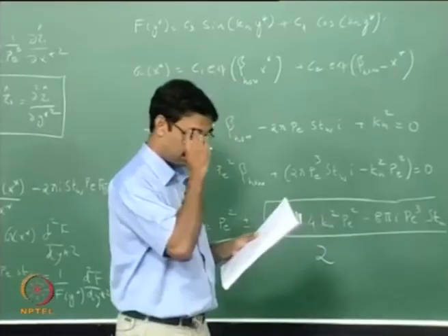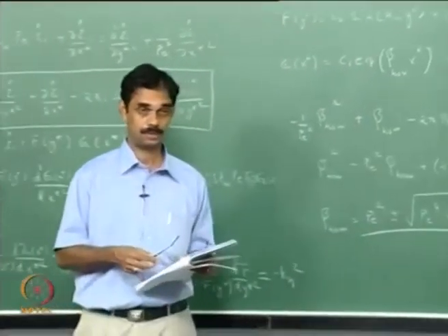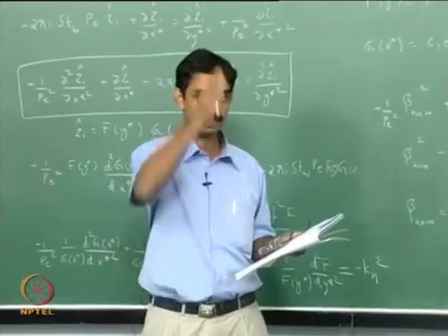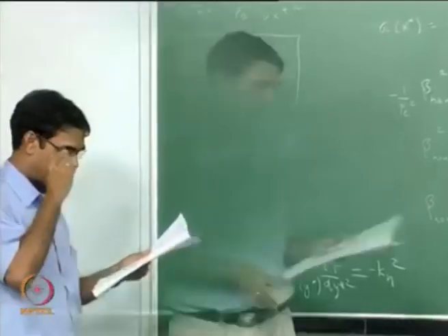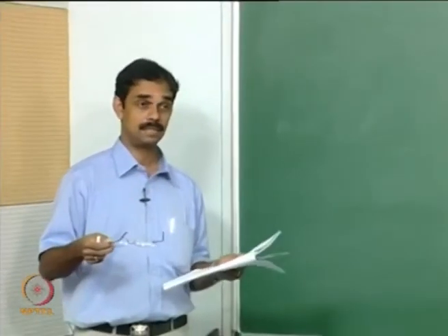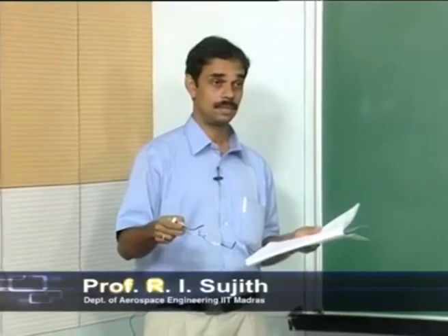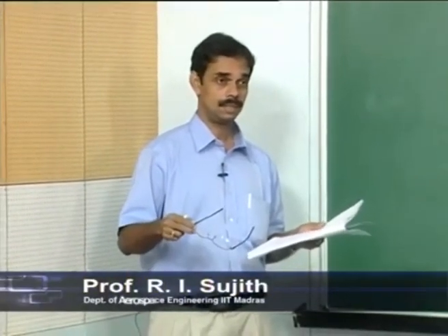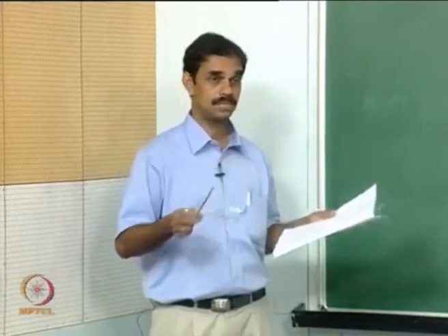Now all we need is to find the coefficients that we can get from the boundary condition at the inlet plane. Since the mixture fractions are fixed, at the fuel slot Z is 1, at the air slot or the oxidizer slot it is 0.